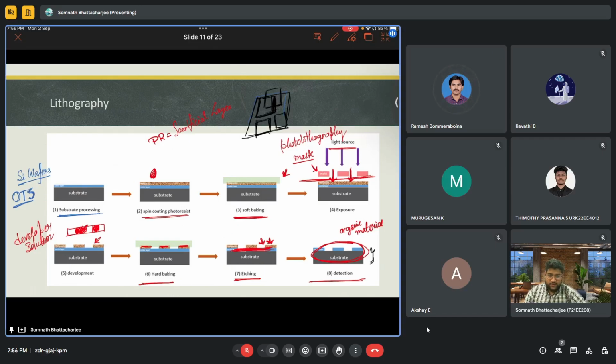So this is only a single layer structure, but on top of this, let's explain a bit maybe. If your created structure is like this, on top of this you will create another layer, but that will be a purely sacrificial layer which will be removed afterwards. If we need a structure like this, you will put a sacrificial layer here, and deposit a layer like this. So you will pattern this afterwards, and the layer will look like this. So here there will be something, there will be a sacrificial layer on top of this.